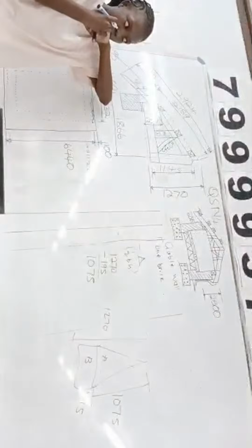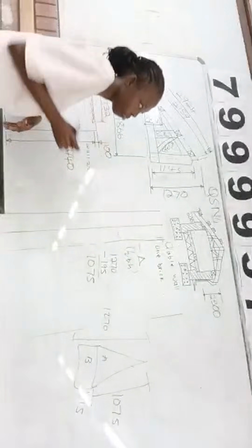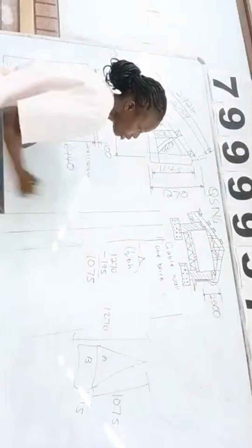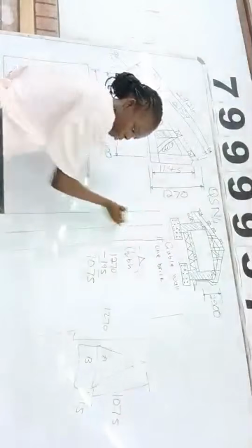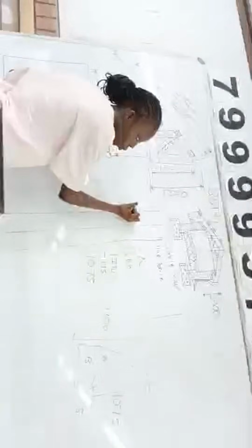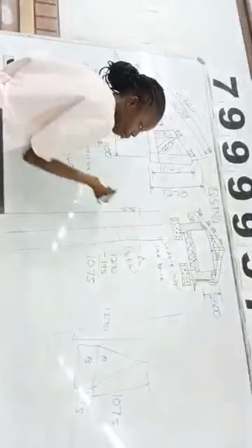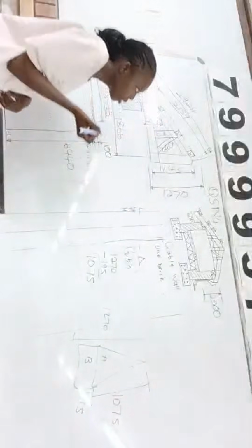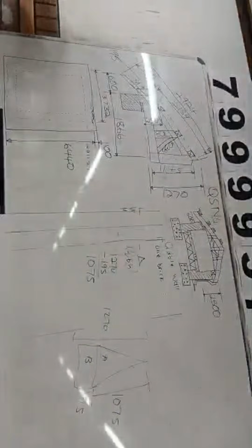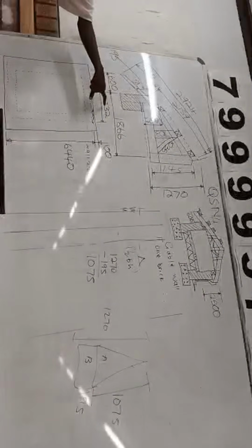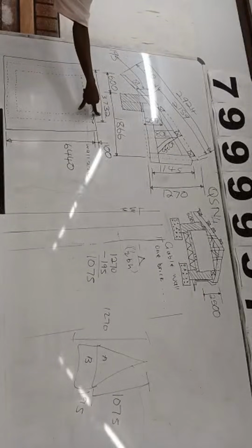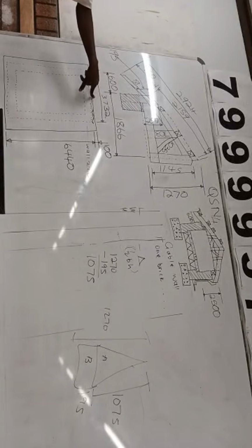So now we come here to the takeoff. On the takeoff part, you're going to say my base. Remember, the format here to write is length, width, and height. We don't have the length, we have a width. What is our width here? We have 3732. This 3732 is the base of your gable wall.